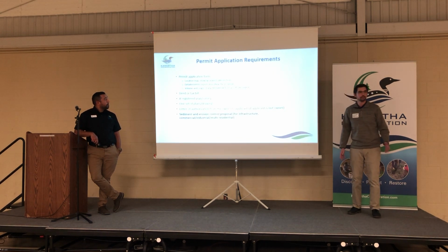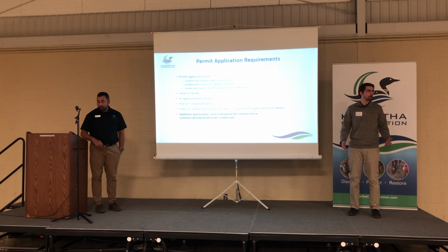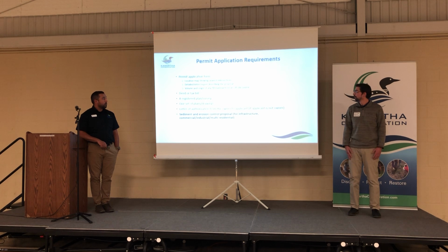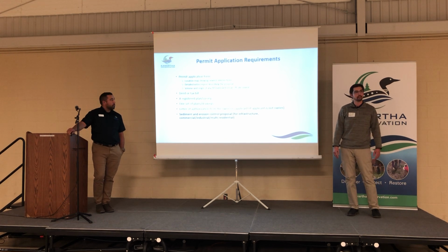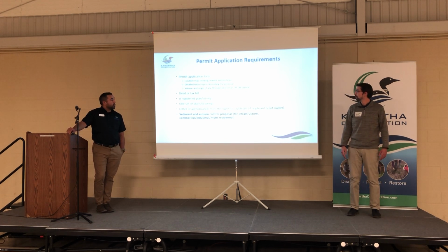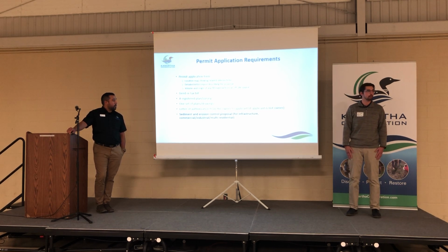So on the Kawartha Conservation side, permit application requirements include a complete permit application form. If you're applying through our website using an online form, the form does include these 3 items: a location map showing nearest intersections, a detailed letter or report describing the proposal, and the volume in cubic meters or yards and origin, so the company name or location, from any fill material that's being imported to the site. This includes granular sand topsoil, and it does not include any poured concrete or backfill native to the site.